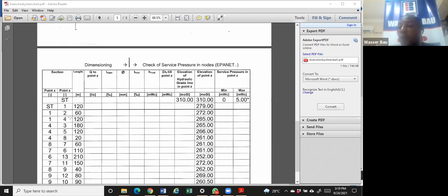And then he has to know the demand, because you, the engineer, the demand is what will help you determine the diameter of the pipe. Without the flow, without knowing the required demand, you cannot determine the pipe. Yesterday, I told us that for you to design any pipe network, whether gas, oil, sewer, sewage, you need to know the flow.